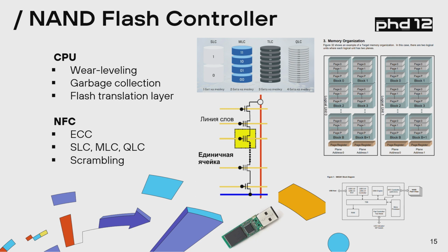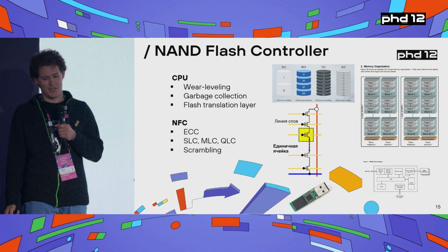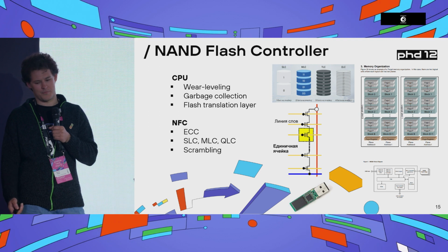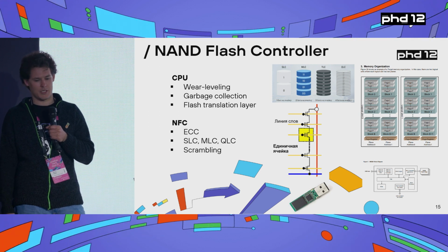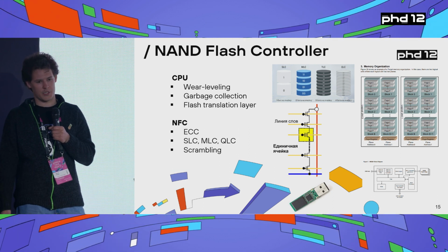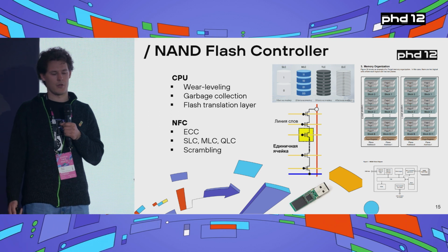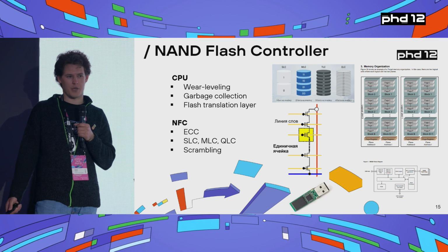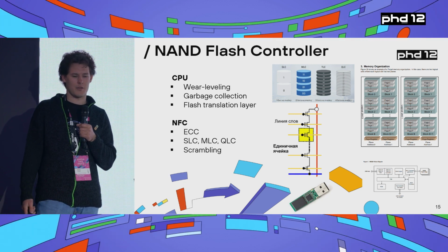Again, people don't tend to think much about it, but even dealing with the regular NAND memory will require a lot of time spent, say, in preparation, because you need to assure that lots and lots of functions are indeed supported. So I'm showing some of the functions you can find in a NAND flash controller. So I've broken it down into two groups, showing what the flash controller itself is responsible for versus the functions of the CPU. Take, for example, wear leveling.